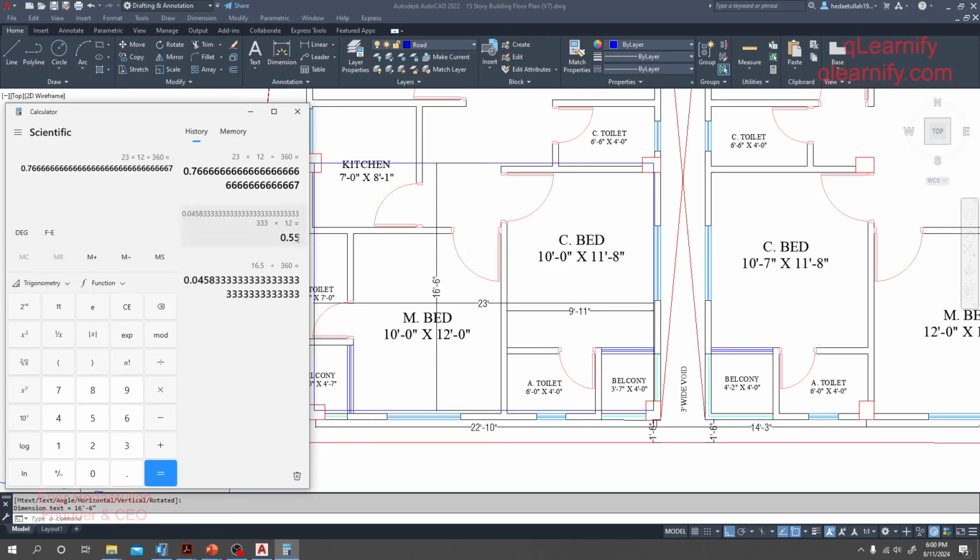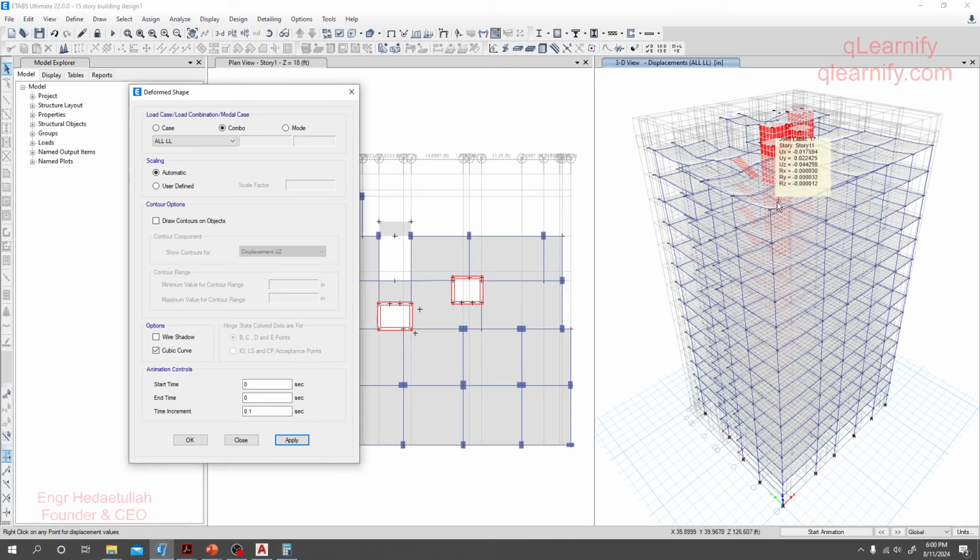So our short direction limit is 0.55, but if we go to our software, we may see that for overall, I mean any part of that structure, the maximum is 0.19, at height 184. So maybe this is the height, 126 I think, for that slab.